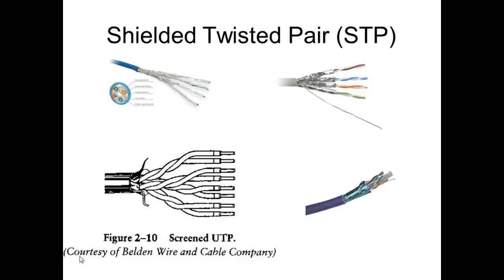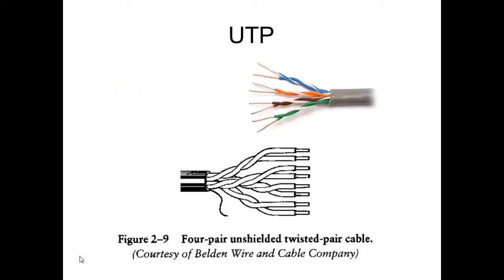Now, on that twisted pair, what if you cut back an inch? It's still twisted. Yeah, it's the same. It's not set by the jacket. It's set by the spacing in this cable right here. So it's not how far you cut back this jacket. This jacket has nothing to do with the impedance of the cable.